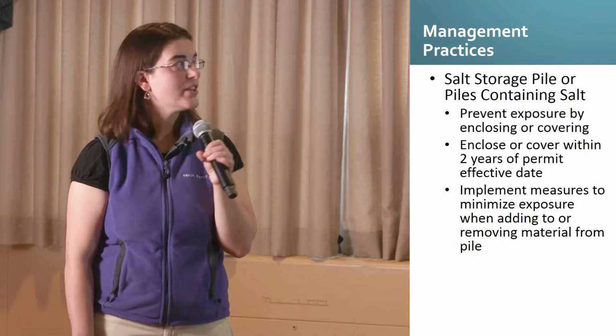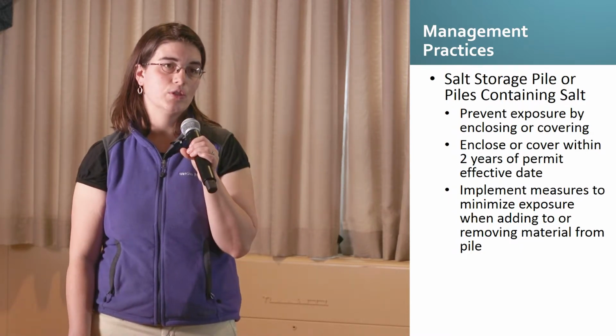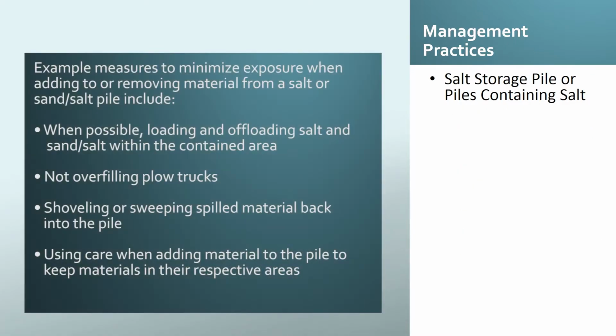And then you need to implement measures to minimize exposure of the material when you're adding to and removing material from the enclosure. Example measures to minimize exposure when adding to or removing material from a salt or sand salt pile include, when possible, loading and offloading salt and sand salt within the contained area, not overfilling plow trucks, shoveling or sweeping spilled material back into the pile, and using care when adding material to the pile to keep materials in their respective areas.